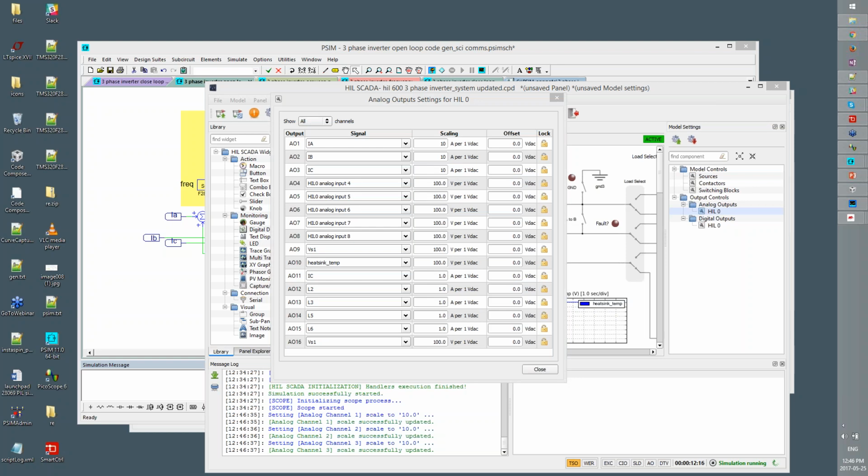The ADC process is run inside the DSP. Yes, the analog to digital conversion is happening with the TI's ADC. If you wanted to run an external ADC, that is possible with PSIM. PSIM has the ability to set up an SPI interface if you want to run an external ADC conversion. If Chris has comments about the accuracy of the ADC on this, then now would be a good time to mention them.